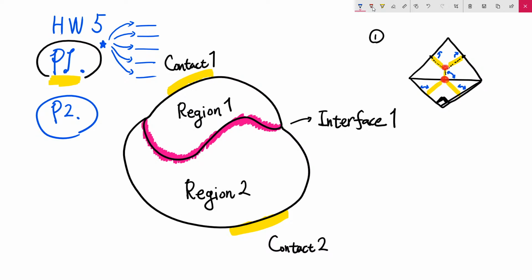So if we calculate, for example, the flux between phi of the first node and second node, we will consider phi 2 minus phi 1, divided by length L between 1 and 2, and multiplied by area of 1 and 2.